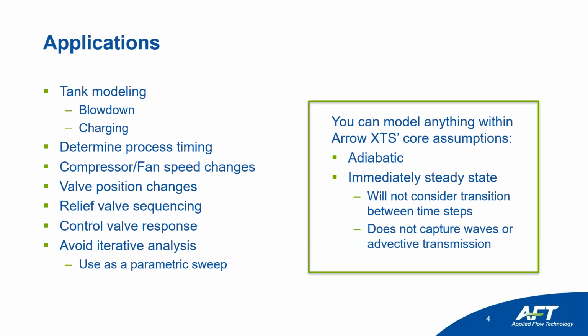But we aren't trying to capture things like pressure waves or advective transmission, where things are going to travel along the fluid as it moves with the system. For example, if you were pumping in a hot fluid and then you had a step change and you're pumping in a cold fluid, that's what I would call advective transmission, where those parameters are going to follow at the velocity of the flow rate. So it's not capturing that.